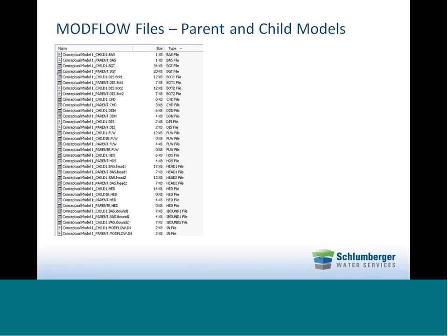I mentioned that as part of the conversion of the MODFLOW LGR to the MODFLOW files, it creates parent and child models. For each of the packages used for that model, whether they be the basic package, the discretization, constant heads, or rivers, you'll see a MODFLOW file for the parent and each of the child grids that are generated. The same is true for the results. After running MODFLOW LGR, you'll have an HDS file, a DDN file, and an LST file for the parent grid and for each of the child grids.